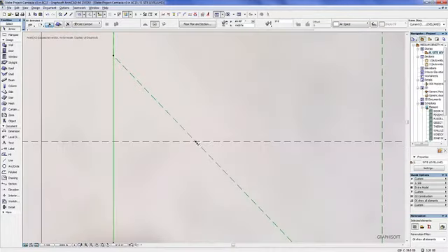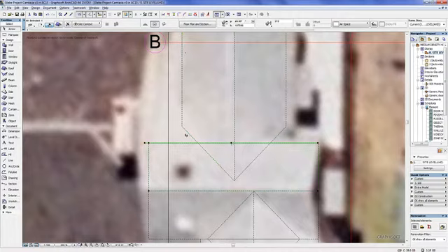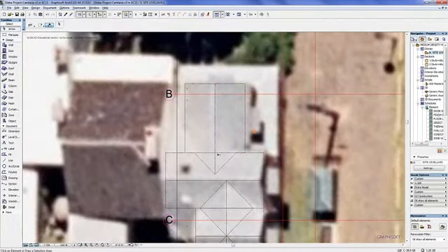So notice how it's got to be snapped to the intersection between this roof and the edge of itself here. Then click on the dot, make sure it's move node, and then click. Okay, then click on the dot and then move node, make sure it's move node, which it is, and then click. You may find it helpful to hold down the shift key so that it's constrained to straight.